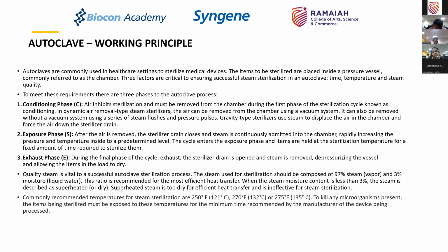In a real-time manufacturing operation, you have to carry out maybe about 5 or 6 cycles, or sometimes even 7 to 8 cycles in a day, in a given number of shifts. So in that situation, if you have to wait for the chamber to cool down and to dry, it will take a long time if you allow it to happen naturally. So you have to use mechanical means of vacuum and air injection into the system to be able to dry the items, and also to remove the steam and cool the area, because you can't remove an item when it is hot.